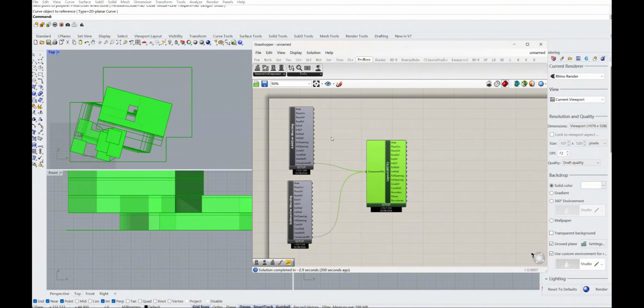Let's say you already have two building massing generated components, it means at least 50 or 60 parameters. If you have too many generated components, there will be more than hundreds of parameters, which will overwhelm the evolutionary algorithm in solving the problem.